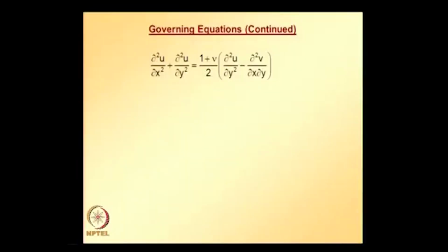We derived this second order differential equation starting with the equilibrium equation in the x direction, substituting stresses in terms of strains using the stress strain relation, and then substituting strains in terms of displacements using strain displacement relations. After a couple of mathematical manipulations we finally arrived at this equation.